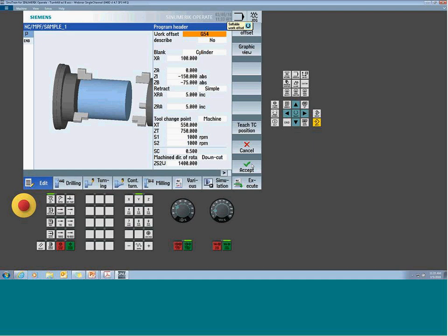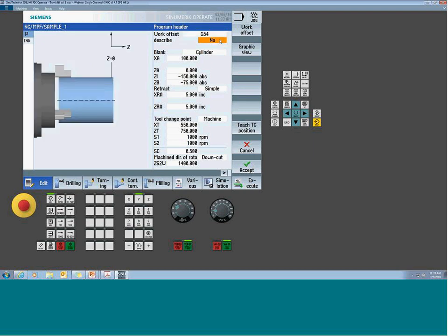Like I just mentioned, there's really nothing unique here. If you're at all comfortable with driving a machine with a sub-spindle, these are the same features and functions. So the field for the primary work offset, if I have a known value for the part sticking out, would be the total offset from the spindle face all the way out to the work offset.